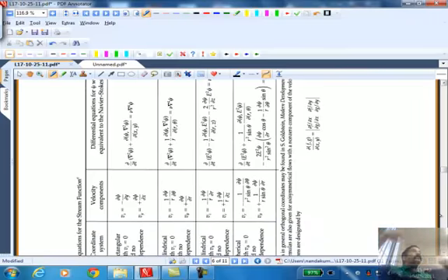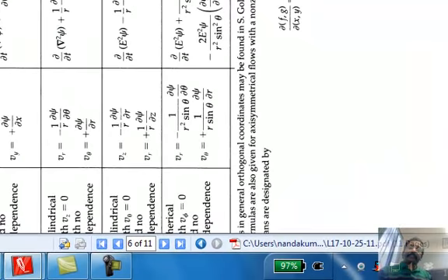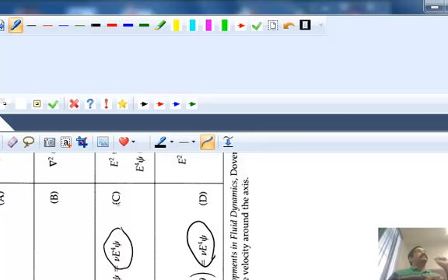After going through these processes, eliminating the pressure, introducing the stream function, and eliminating the velocities, these are the Navier-Stokes equation in terms of the stream function for the full Navier-Stokes equation. So it includes the inertial term on the left-hand side and the viscous term on the right-hand side. But for us, all we need is this viscous term, E to the power 4 psi. So a fourth order equation in a single variable psi. So if I can solve for that, then I've solved the problem completely.